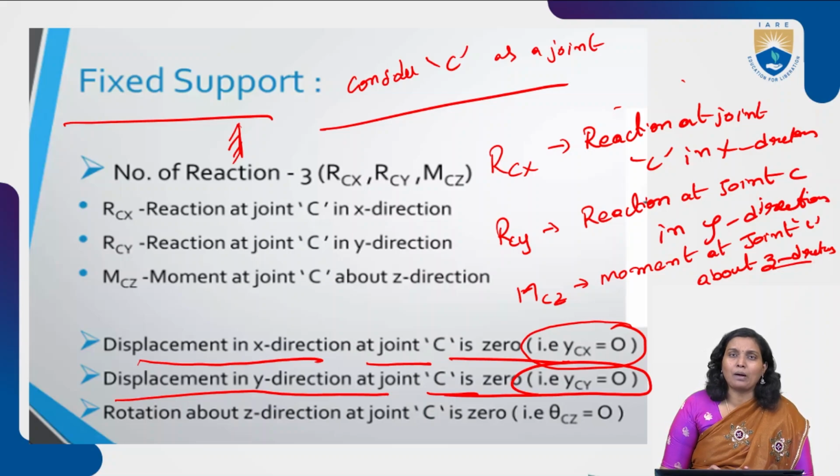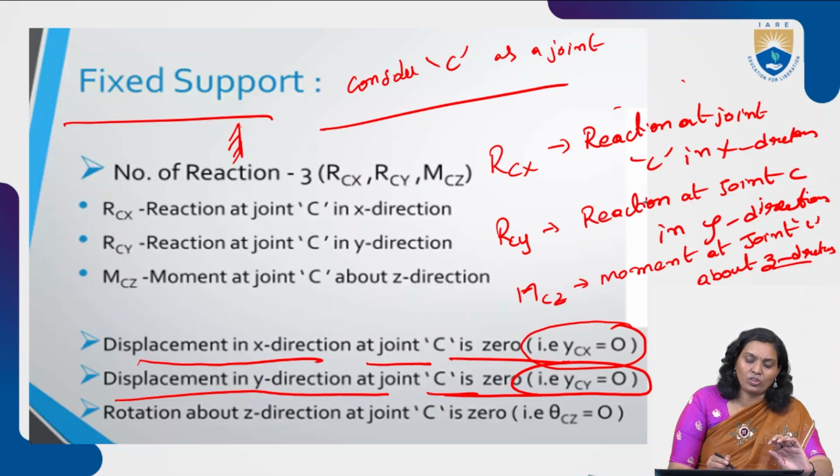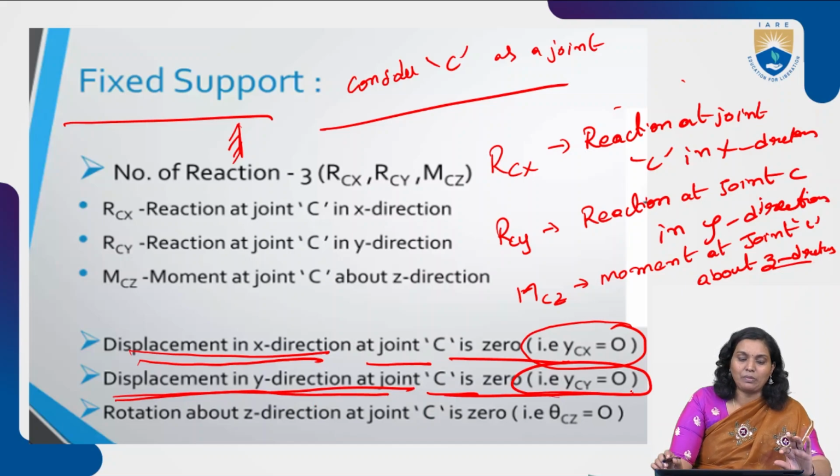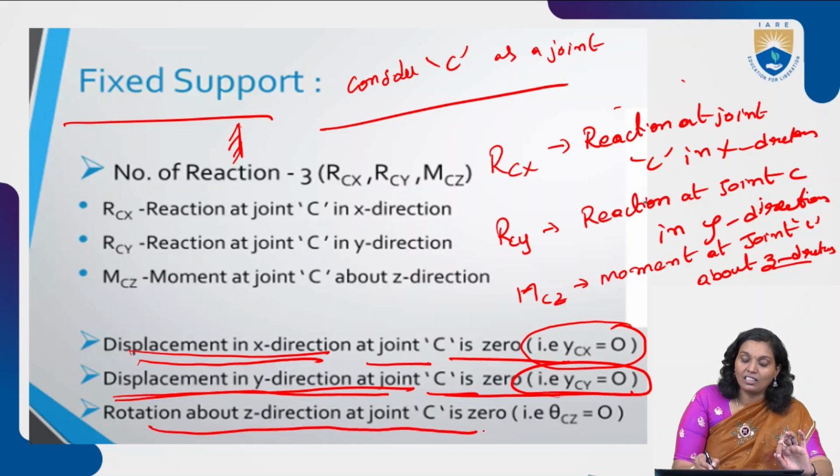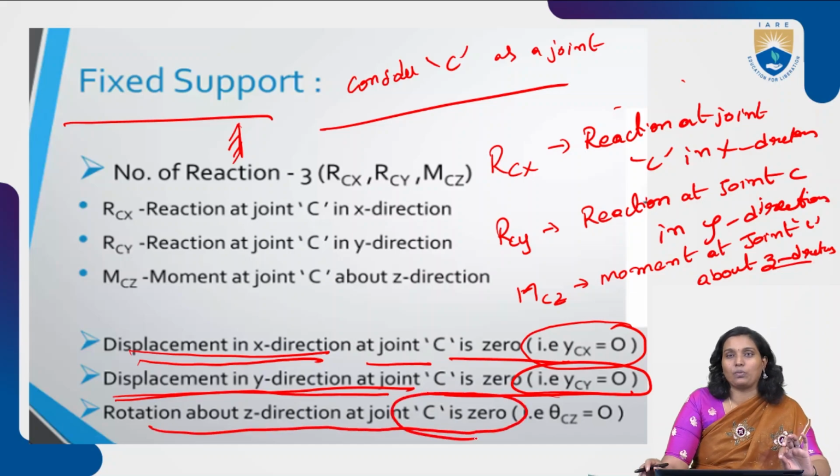Coming to the displacement point of view, for the fixed support the displacement in X and Y directions is 0, and the rotation about Z is also 0.